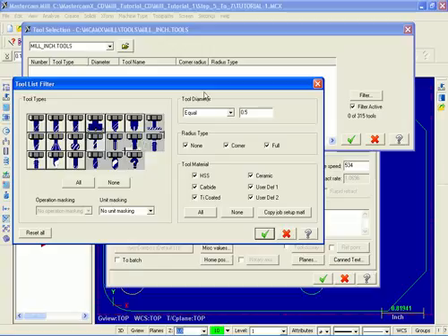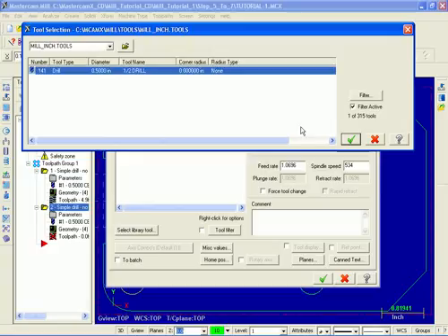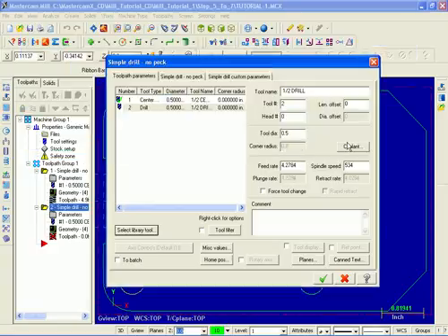Moving over to the right in the tool diameter section, I'm going to select the drop down, and we have a series of different options here. Ignore, equal, less than, greater than, between. I'm going to keep it set to equal and leave the value at 0.5. I'm going to hit the check mark, and our 1/2 inch drill has been filtered out. I'm going to select it and then pick OK.